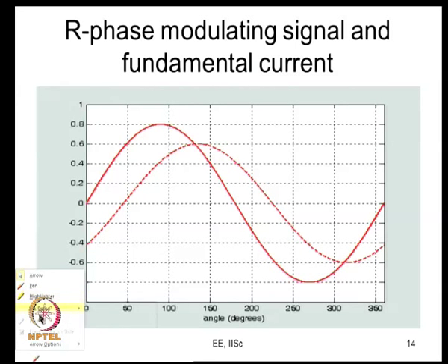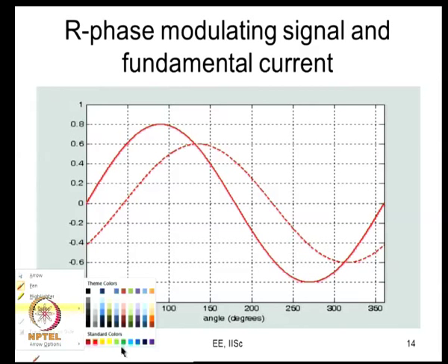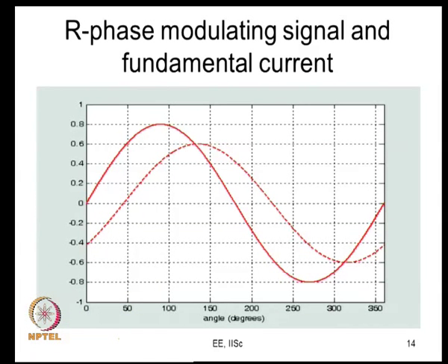Now, what is our simplifying assumption? We have simplified that the loss is proportional to the current that is being switched. So, we say that if the current being switched is 0, the loss is also 0. So, if the current being switched is so much, again here. So, let us say how would this switching energy loss vary?